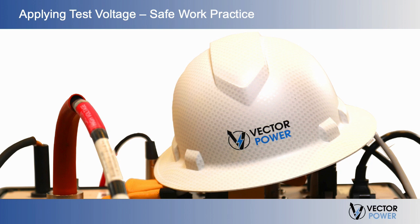After discharge, tested items should be firmly shorted out with a shorting link until required for use. This is to guard against any stored dielectric absorption charge subsequently being released, thereby raising the voltage to potentially dangerous levels.